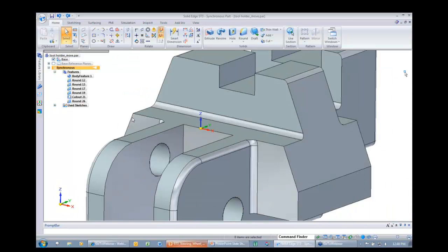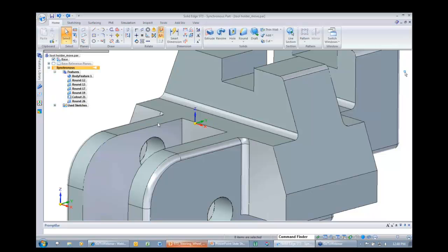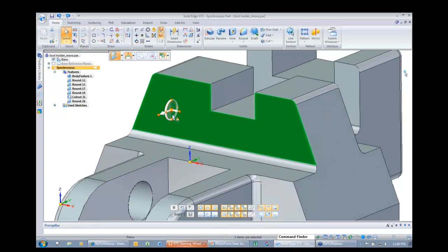If I click on this face, this front face, and I want to lie the steering wheel down, if I hold down Shift and left click inside the torus, which is the tool plane, notice how it just lies that steering wheel or that torus right down on the face. So if I want to do a copy and paste operation, that's a nice tip and trick. It kind of switches the primary and the secondary axes. If that's the orientation I want, notice as I just hold my left mouse button down and drag it around, notice how it flips orientation like we saw earlier.